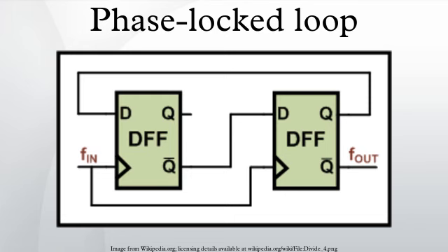Some data streams, especially high-speed serial data streams, are sent without an accompanying clock. The receiver generates a clock from an approximate frequency reference, and then phase aligns to the transitions in the data stream with a PLL. This process is referred to as clock recovery. In order for this scheme to work, the data stream must have a transition frequently enough to correct any drift in the PLL's oscillator. Typically, some sort of redundant encoding is used, such as 8B/10B encoding.